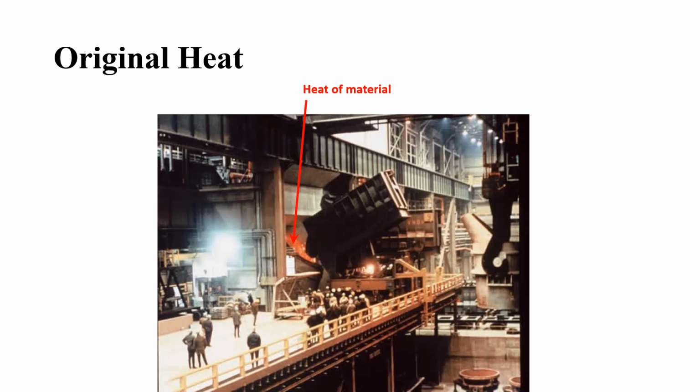The finished steel is then turned into raw product forms such as billets and slabs. Manufacturers of pipe and tubing then order either billets that they use to form into seamless pipe and tubing, or they order rolled sheets from the slabs which they cut into skelp, which are thinner strips of rolled sheet to form welded pipe or tubing.